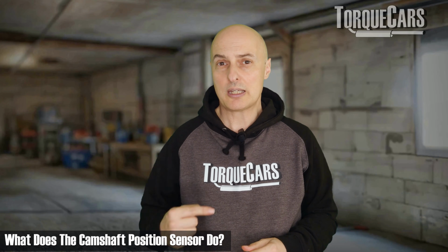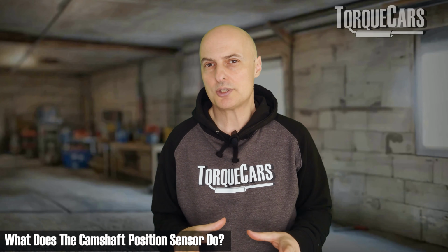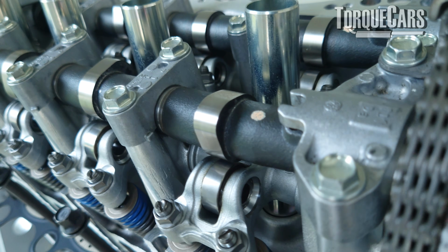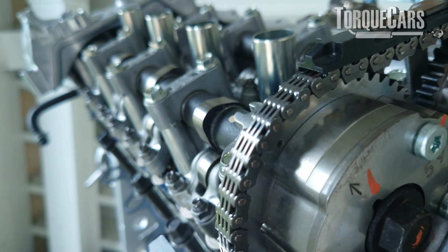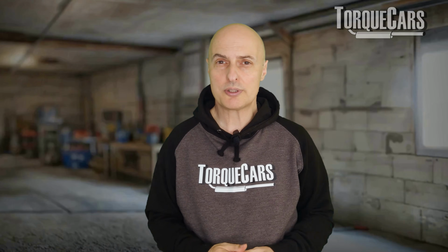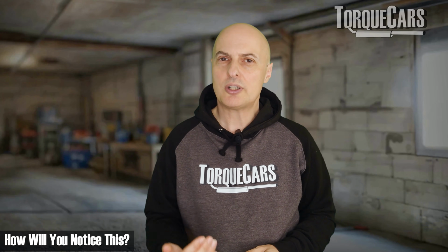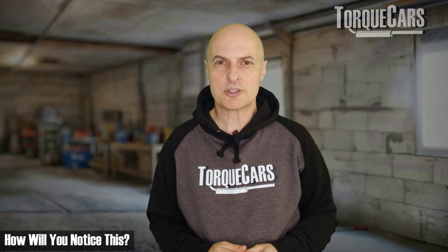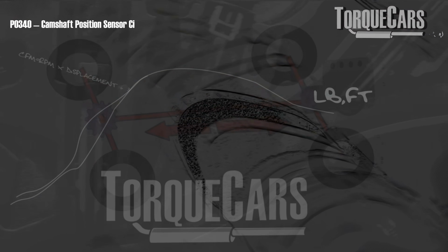The camshaft position sensor tells the ECU where the camshaft is and helps it to make calculations and diagnose where the anomalies are actually occurring. When the sender fails or it gives an intermittent signal, the ECU is going to panic. It's going to throw the car into limp home mode to protect itself. You're going to notice this as a misfire, the engine idling erratically or misfiring under acceleration. This will usually start off as an intermittent fault and it will get progressively worse.